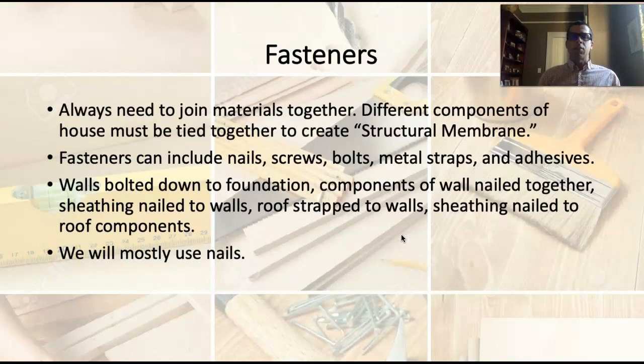Lots of different fasteners we're going to use to fasten the house together. One of the concepts I want us to wrap our heads around is this idea of the structural membrane, or another term that gets floated around is the load path or load transfer. What that means is we are tying all of the different components of the house together. We're attaching them all together with mechanical fasteners, and the weight of that entire structure travels through certain components in the house all the way down to the foundation.